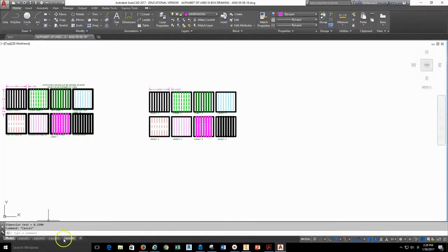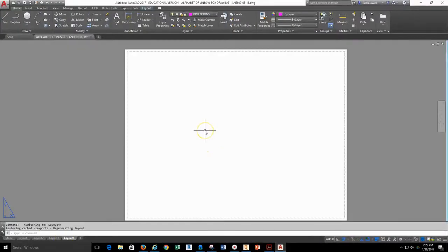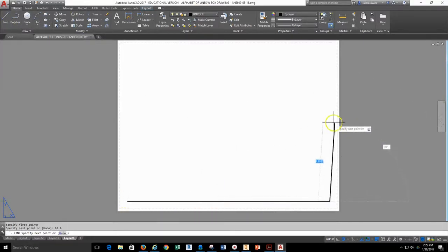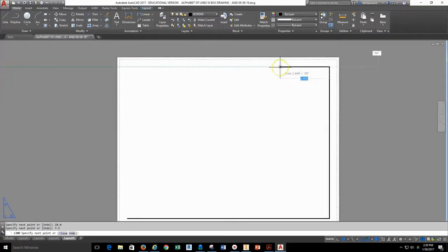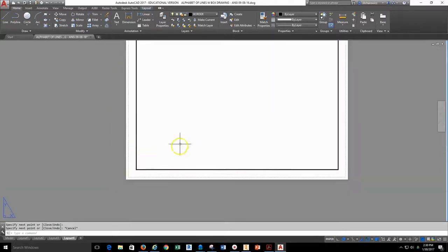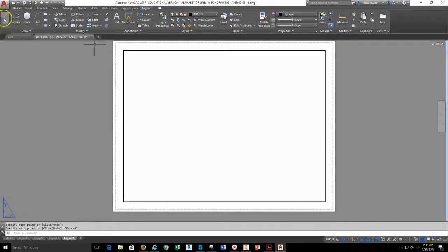So if I go to AutoCAD and select a blank layout, I can then go ahead and select my border line, as my border line is the layer that I will create for my title block, and then I just start drawing in the title block. Title block should be centered approximately, within these dashed lines, as those hidden lines here, or I should say these dashed lines are the printable margins of the paper, and then you just start drawing directly on this paper for your title block.